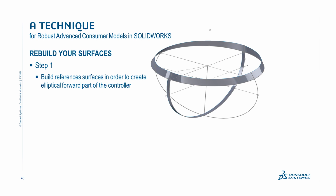Okay, so let me step through this model and we'll just talk about it through PowerPoint and also through SolidWorks and showing it live. So if you look at any of my advanced models, you'll notice I use a lot of reference surfaces. Reference surfaces are valuable for creating other surfaces. They aren't part of the model, but they help guide your primary surfaces.